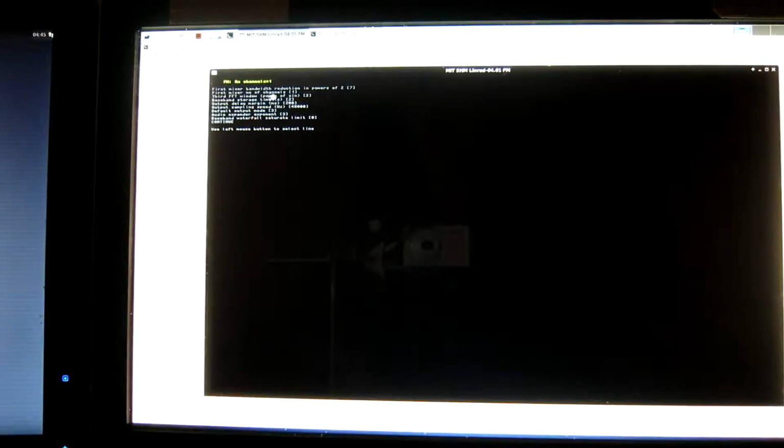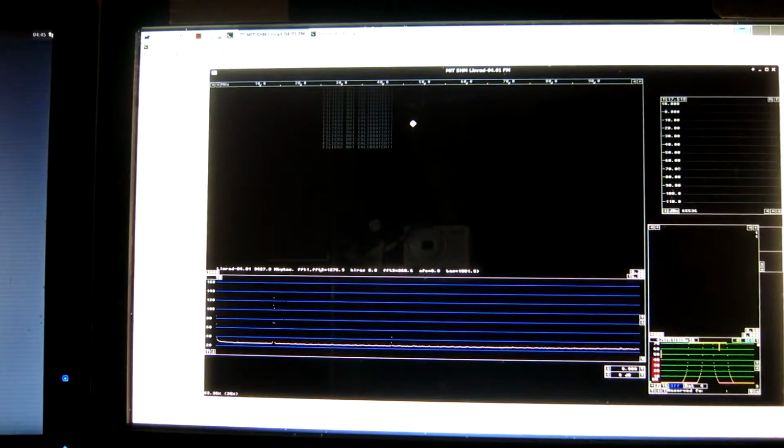The third FFT window is 2. That's not a particularly good window, but we don't need very sharp, very steep corners on the baseband filter for anything I have been doing here. And we are back at this.